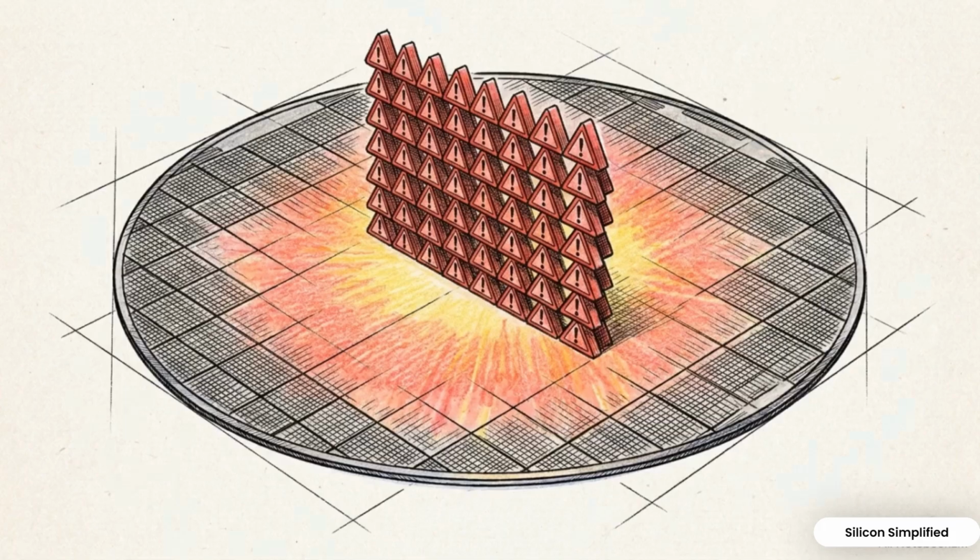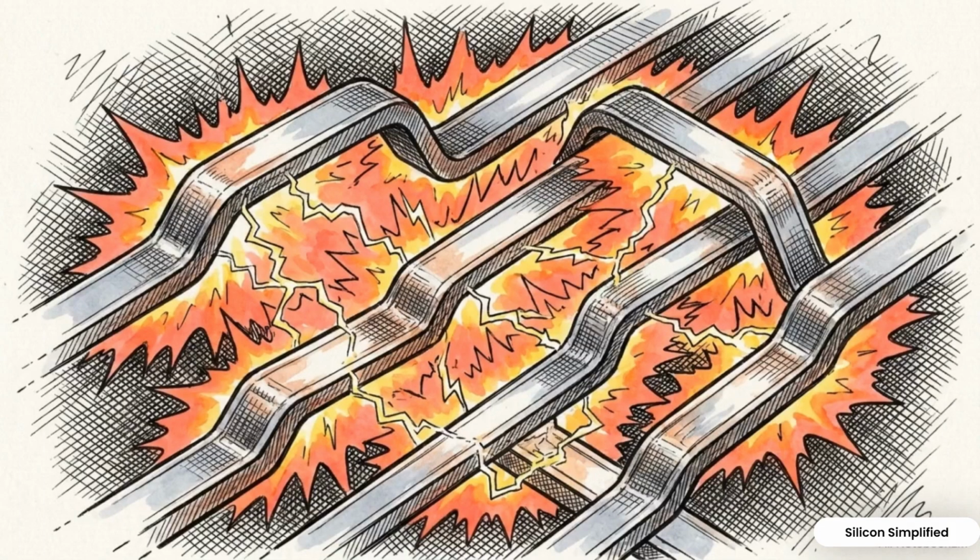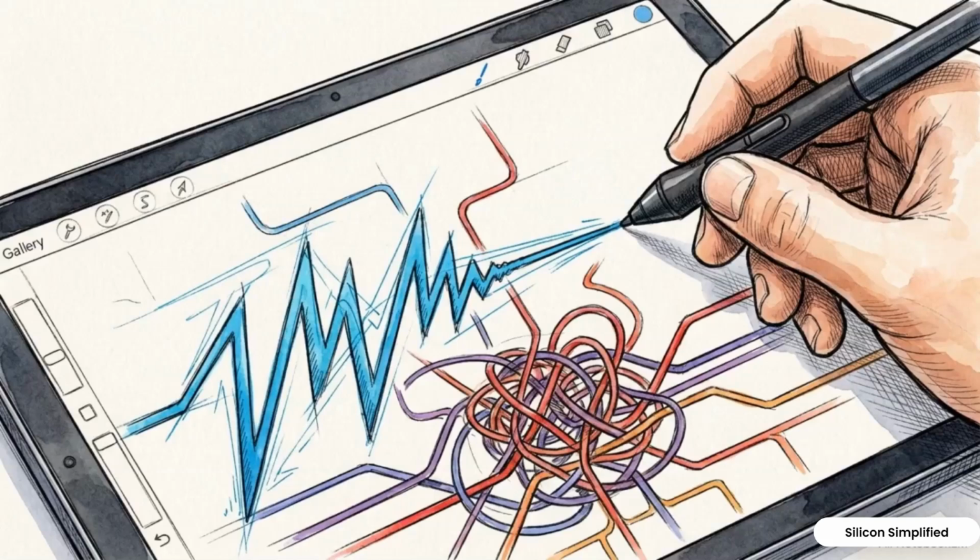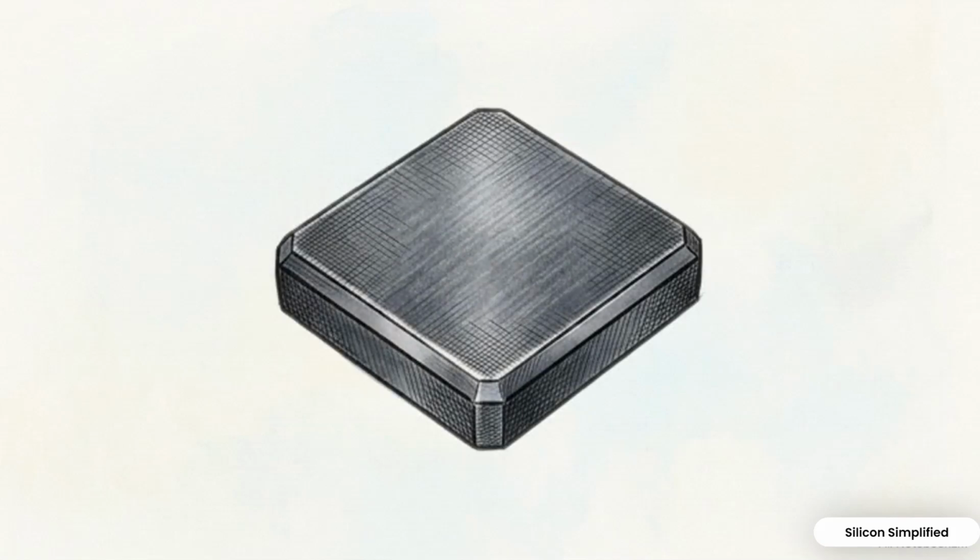While older nodes allowed for more linear scaling, advanced nodes like 5 nanometer and 3 nanometer present a significant physics wall. Extreme interconnect resistance, parasitic capacitance, and severe thermal density at these scales shatter the assumptions of traditional sequential design pipelines. Achieving design closure at sub-5 nanometer dimensions is an NP-hard problem where fundamental material physics frequently counteracts the engineer's design intent. Floor planning establishes the chip's structure.